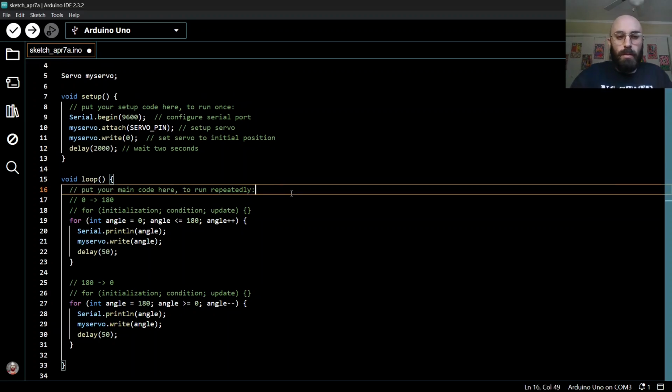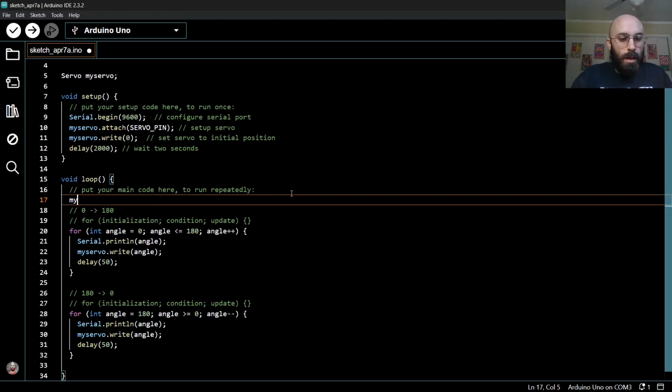Another servo function is servo.read, and what that does is return back some information from the function. So functions can both take some values as arguments, as inputs to this black box, and then do something with them, and some of them can return back information, and we call these return values. myservo.read returns the current position of our servo. Other examples of things that give us return values are digitalRead or analogRead. Those both give us the values that we read from that pin.